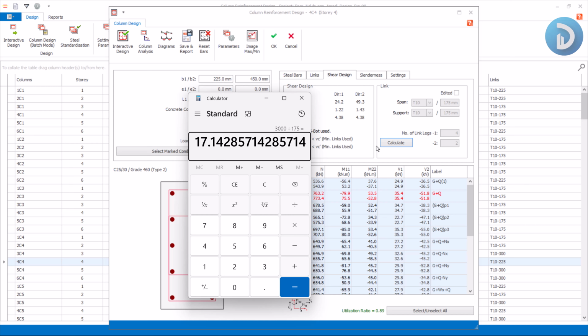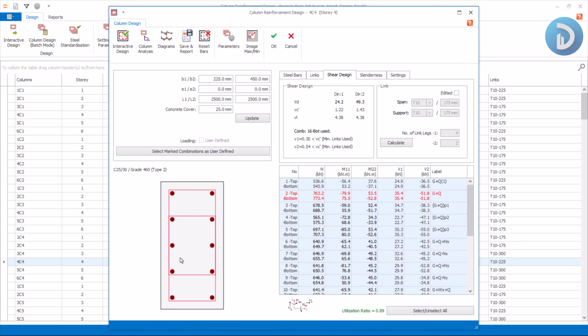So you can compare the cost of this additional reinforcements, let's say you can compare the cost of this Y16, compare it to the cost of 6 numbers of Y20, and also compare the cost of your link. So this is what can make you come out with a cost economical design. But you shouldn't forget that your first principle is ensuring what? Safety, right? So the column is safe in both cases. It's actually safe in both cases.